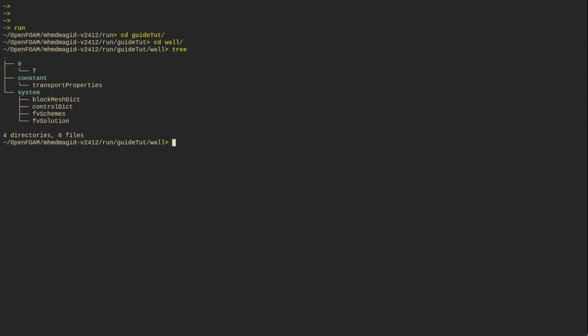So first things first, we are going to determine the domain where the heat equation will be solved, and then generate the computational mesh. Actually, these two steps can be done using the blockMesh tool, as blockMesh allows us to create the domain and generate its computational mesh.